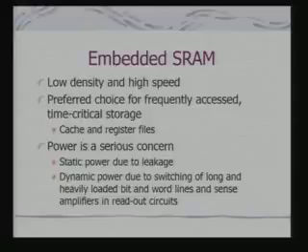In a static RAM, what are the sources of power loss or power consumption? One is static power loss due to leakage, because you have seen the transistors on the path. So there will be a leakage current even when you are not actually accessing that memory, because that memory is in an active state. It is storing the data that you have stored. So there would be a leakage current, and that is what we call static power loss.